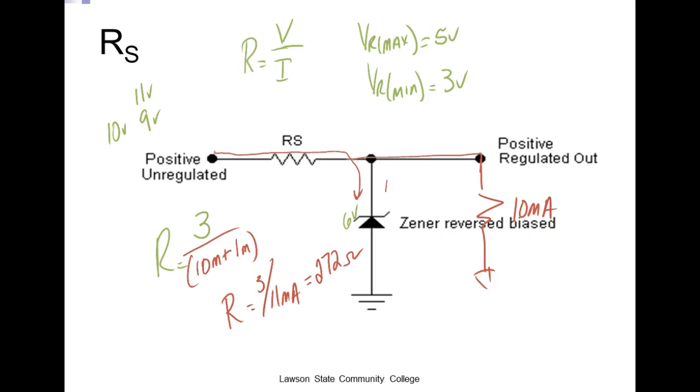Okay, if I round up, we're going to go into IZK. So we're never going to round up. We're trying to move away from the knee, right? You understand that? If I choose a smaller value, we're going to put more Zener current in there. If I choose a bigger value, we're going to move it toward IZK. So even if it falls on a standard value, we always go to the next level.